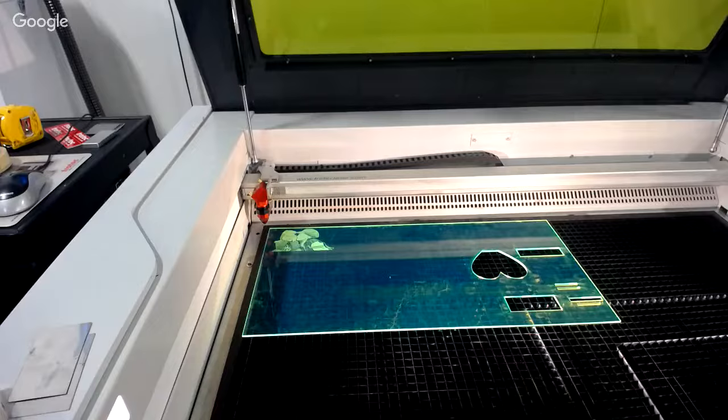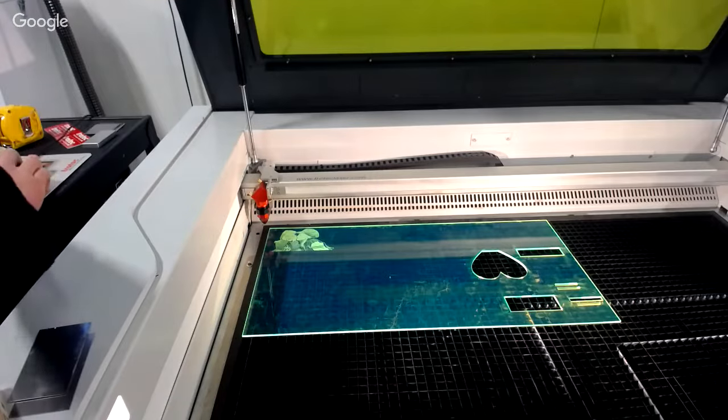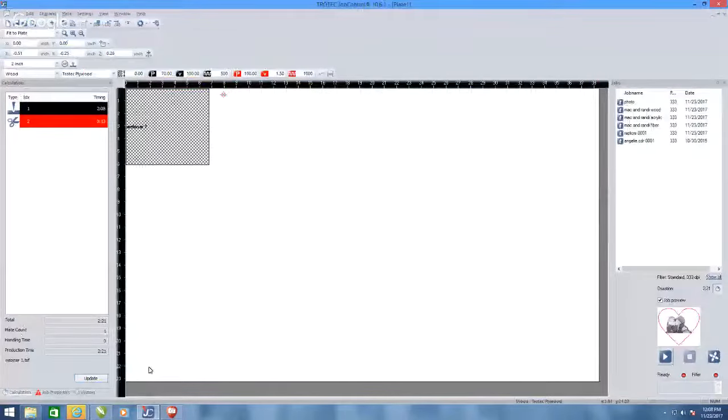We got 2 more questions. Okay, you mentioned adjusting the power while the machine is running. How do you do that? The way we adjust the power while we're actually running is right in job control. When the machine's running, we're in job control here. So what you can do is just type in, let's say I want to go from 70 to 50. While it's running, you could type in 50 power, and that will change the power from 70 to 50.